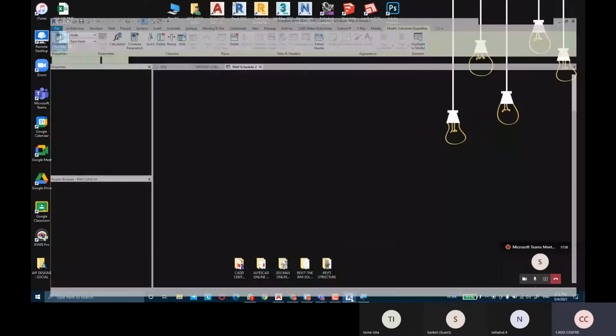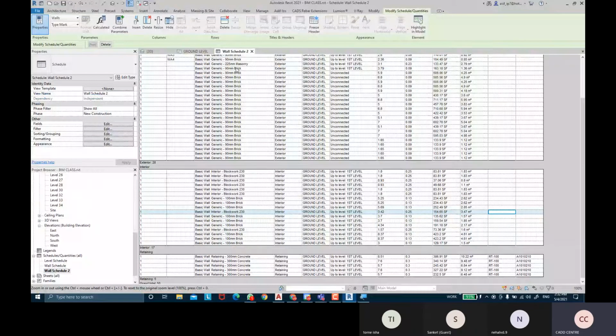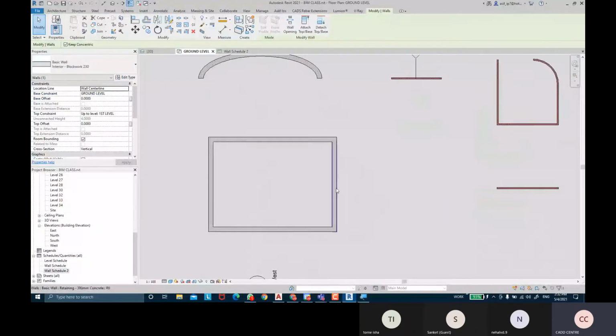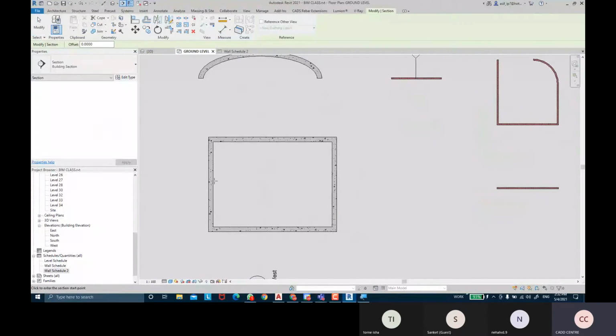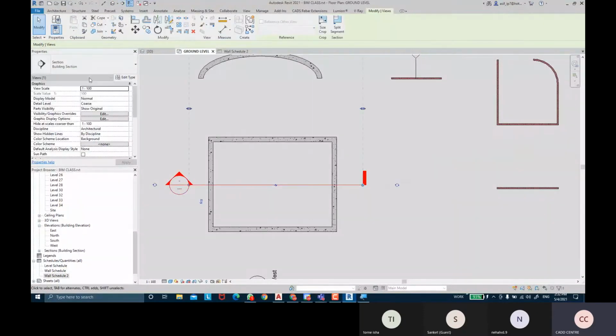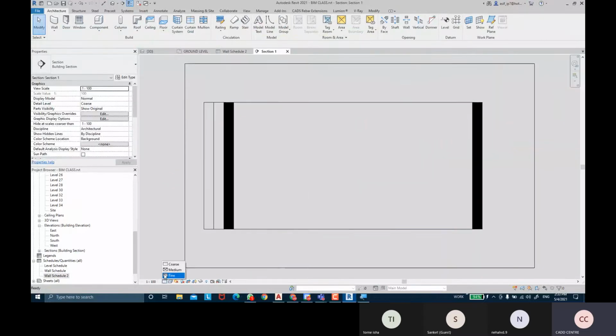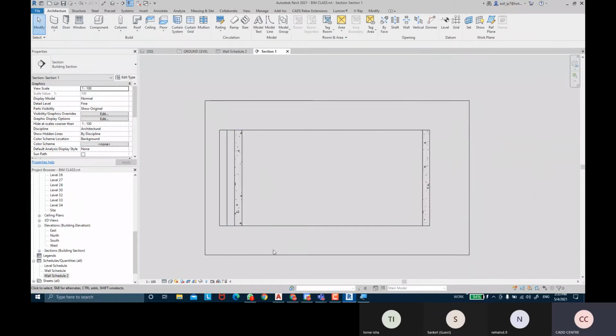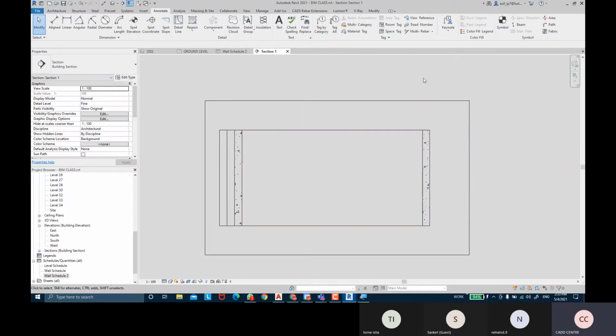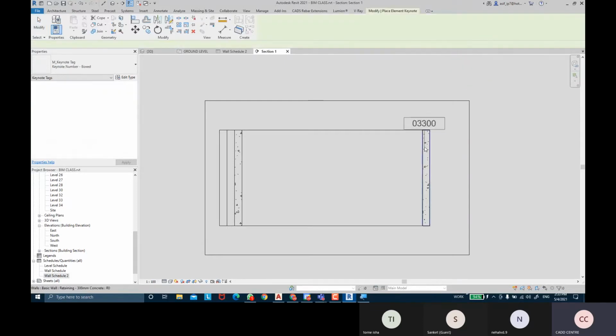And when we take out working drawings for these walls, for example, if we take out a section view of these walls, so this is my section line. I'm going to select that section line, right click, go to view, so it's just to find details. And when I come into the annotate tab and give a keynote, material keynote or an element keynote to it, you can see an assembly code has been put up.